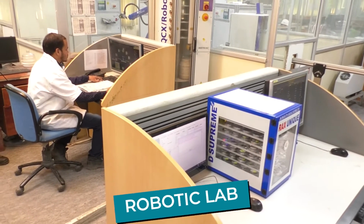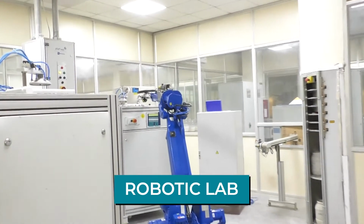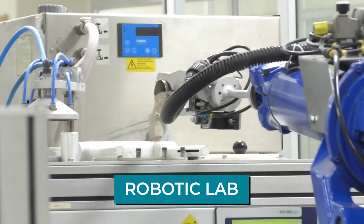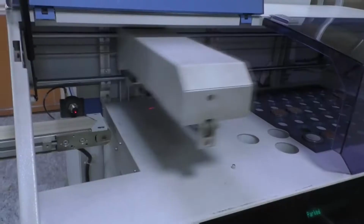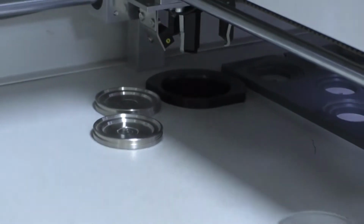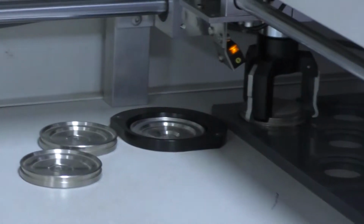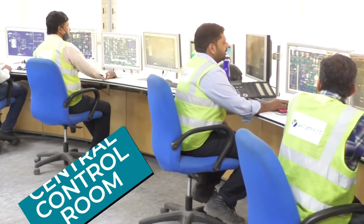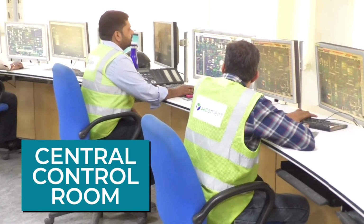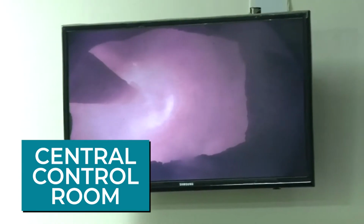Robotic lab. The technology that truly sets the plant apart is the unique, fully automatic robotic lab. It automatically collects samples from various stages at predetermined intervals and pneumatically transports them from auto samplers to the analytical point through well-laid pipelines, where they are automatically processed for pellet preparation and analyzed by highly accurate analytical equipment. Then the analyzed data is transferred to the centralized control room to take corrective action in the manufacturing process whenever required.